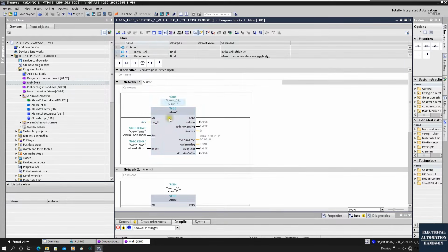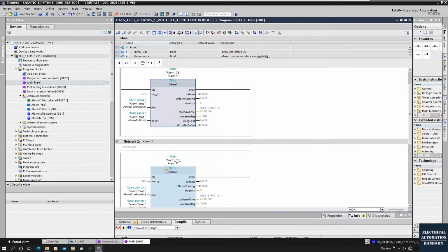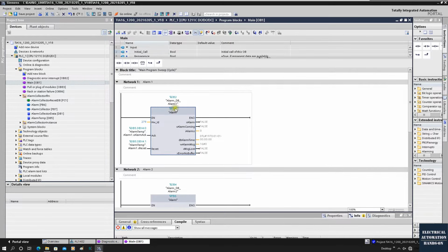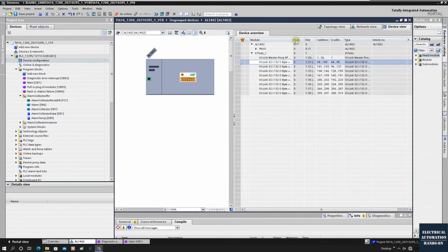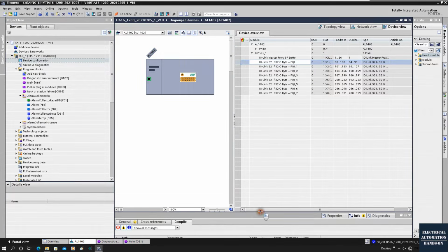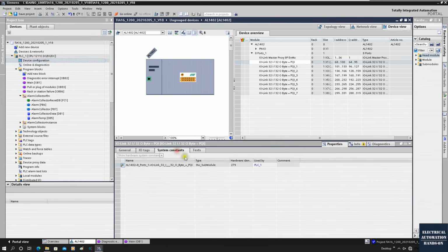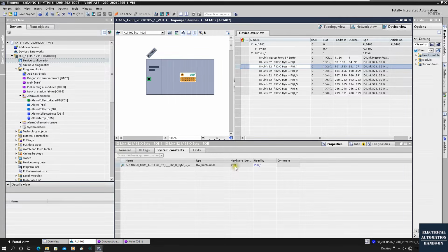This is basically port 1. Each port needs 1 alarm call. So that's why here, if we assume there are 2 ports, 2 IO-Link devices, there are 2 instances using this FB6. This FB6 is the function block supplied from IFM. And here, this hardware ID came from here. If this one is port 1, the hardware ID came from this system instance, okay? And the second one is 280.